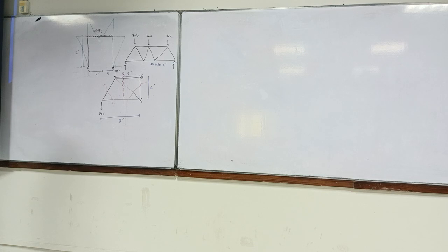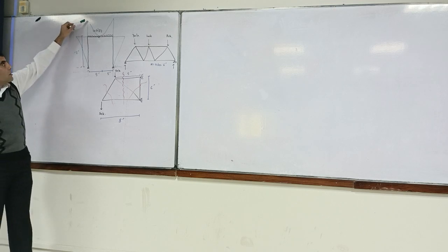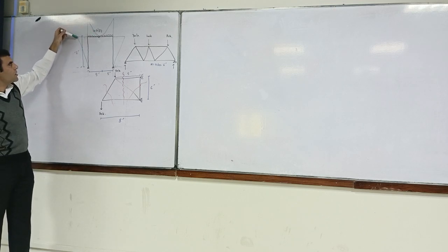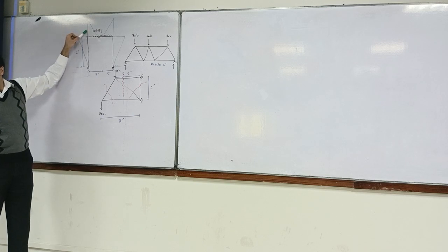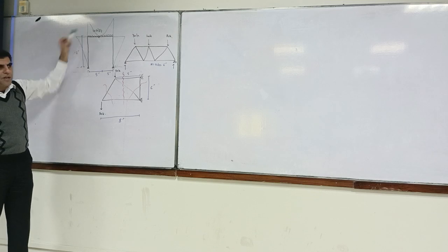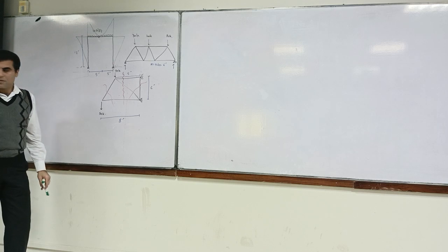So 500 and minus 500, the moment sign, so this will not go down. On the left side the moment reaction was 500 and on the right side minus 500. So the other side should come down. Yes sir. So what will happen? What is wrong in this bending moment? Sir, it is going up from both.